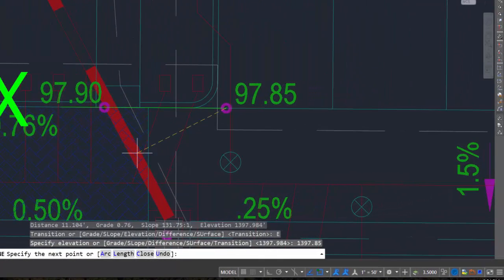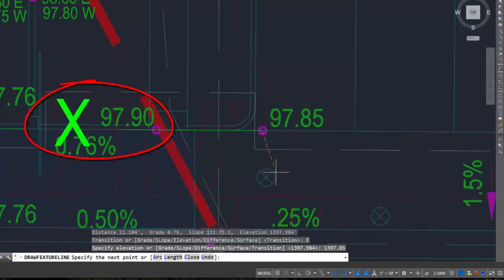And you can notice when we set up our feature line style, we use that fence line. That might be a little bit big. We'll reduce that size a little bit, but it allows us to select those feature lines when we want to do things with them. As you can see, we're drawing those feature lines right on top of the other lines, so we don't have to worry too much about our display order as we're defining things. It just makes it easier for us to manipulate or work with those feature lines.